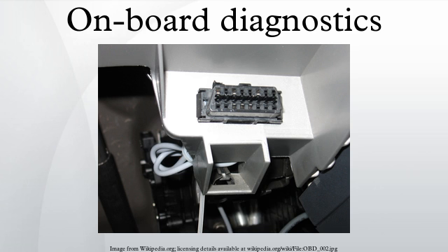In addition to the functions of a handheld scan tool, the PC-based tools generally offer large storage capacity for data logging and other functions, a higher resolution screen than handheld tools, and the ability to use multiple software programs, adding flexibility. The extent that a PC tool may access manufacturer or vehicle-specific ECU diagnostics varies between software products as it does between handheld scanners.